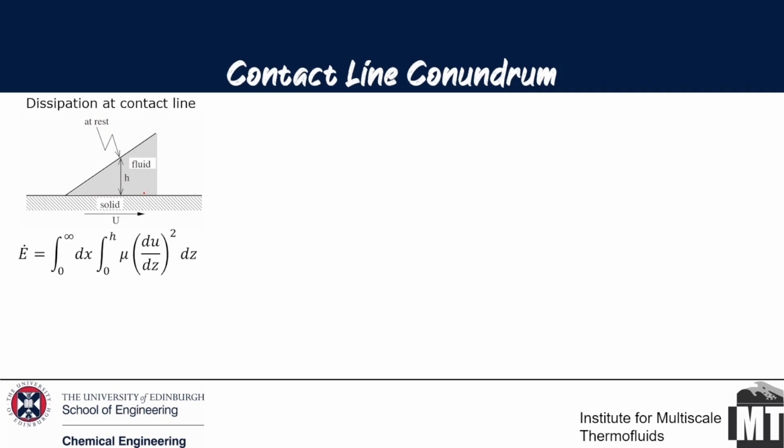At the interface, people do apply a slip condition. It's called the Navier slip condition. And you've got all these weird, artificial definitions. If people use a slip length model, the Navier slip model, I'm sorry, but I don't agree with it. Because the Navier slip model has a slip length, and slip length is anyone's choice. If you're doing simulations and you keep increasing your mesh resolution, you will reduce the slip length. So there's no standard phenomenon. There's no way you can define a slip length. It's very difficult to do that.